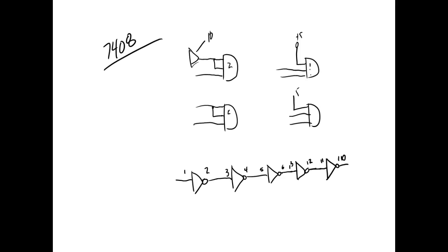So we're just not acknowledging it. It's there, but this scope right here is a 25 megahertz scope, and that's the bandwidth. The bandwidth is what the scope guarantees, the frequency it guarantees to show you at least 70.7% of what's there. Well, the problem is that we're looking at a fall time. So even though I'm looking at let's say 100 hertz, we're talking about the frequency of how fast this thing is falling, right?